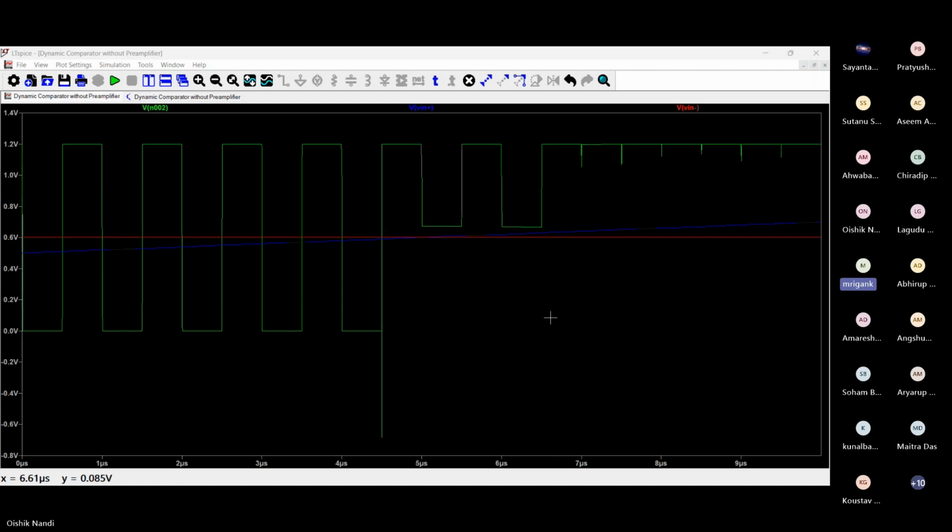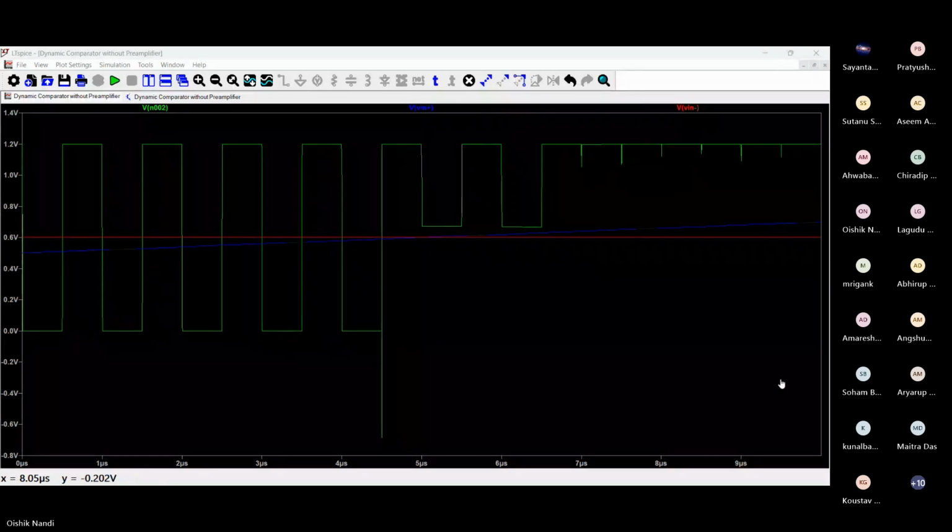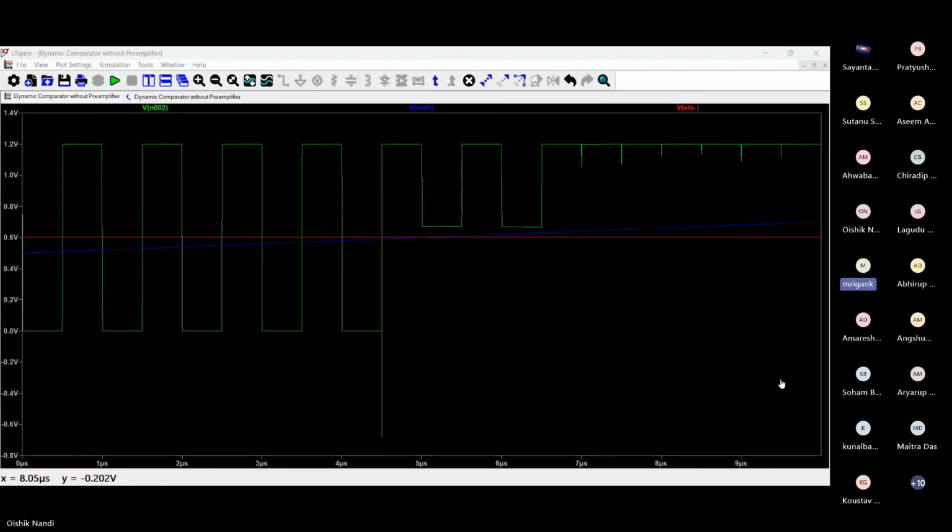When the two nodes are very close, or the input signal is very close, the differential current produced is very close, and it is not able to completely switch. But eventually, in the presence of device noise or circuit noise, it will switch in one of the directions. So for the time being, you can just assume that the resolution will be decided by the point where it is completely switching. That's all. You can just confirm this.